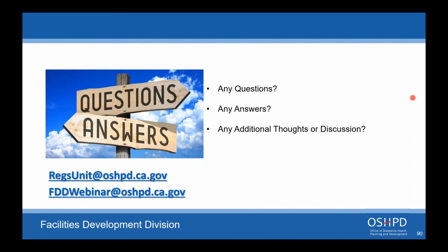The only place I've seen the manual ones is for med gas, because the med gas has to remain operational even after an event. And you can't shut off oxygen or something to a patient that might be on the other side of the wall that's using it. But everything else is going to be an automatic shutoff valve. Perfect, thank you. Next question.